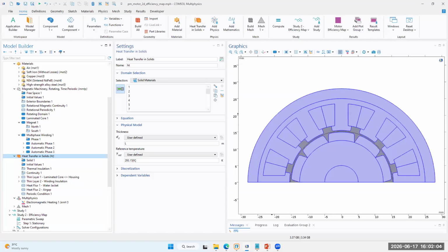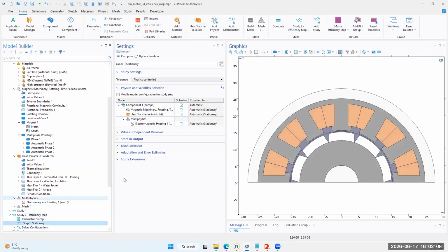Okay. So when we talk about motor modeling, it depends on the type of the physics interface or the physics formulation that we are going to use, and it's also going to depend on the application. So when we are talking about motors, if it is a multiphysics simulation of motors, we always prefer choosing the time periodic interface where you can solve all time frames at once, and there it would be efficient to couple with heat transfer physics.